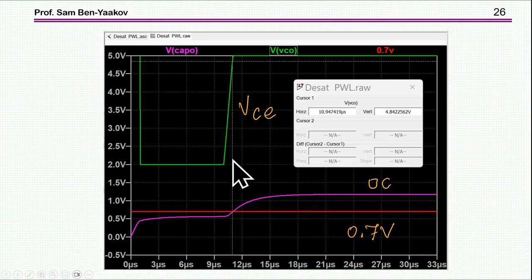And for this particular demo circuit, the voltage will be 4 volt when the actual action is taken, because there are delays, and as I've said, an IGBT can tolerate some of these delays because it's very robust. Other transistors like gallium nitride may not be able to sustain this stress.